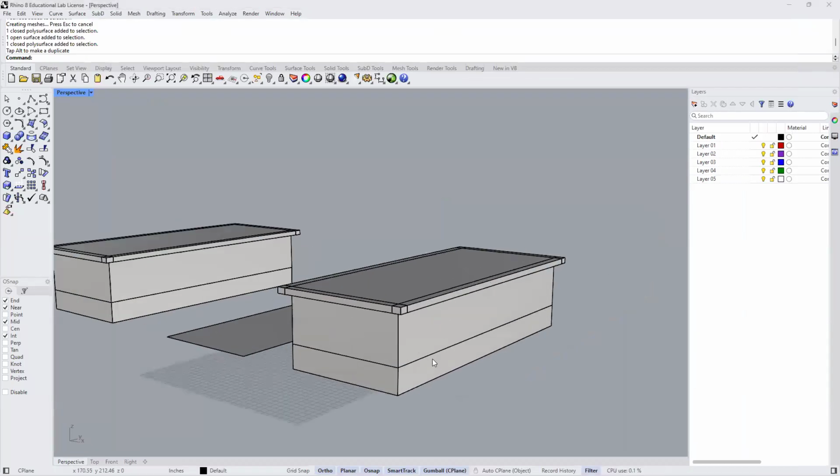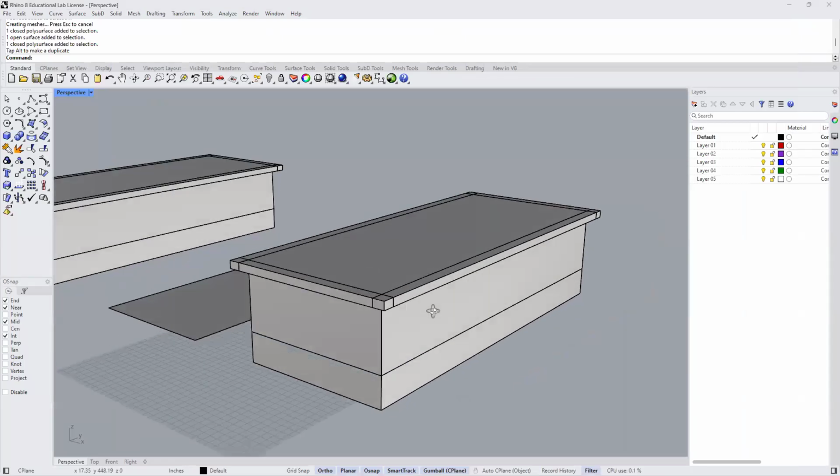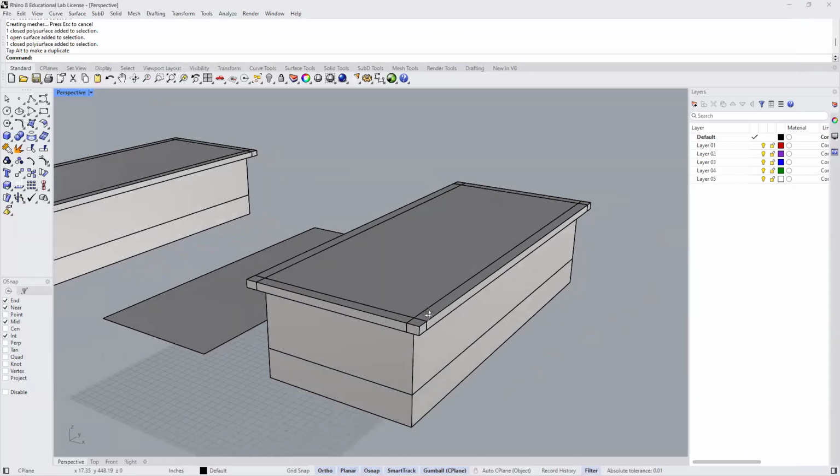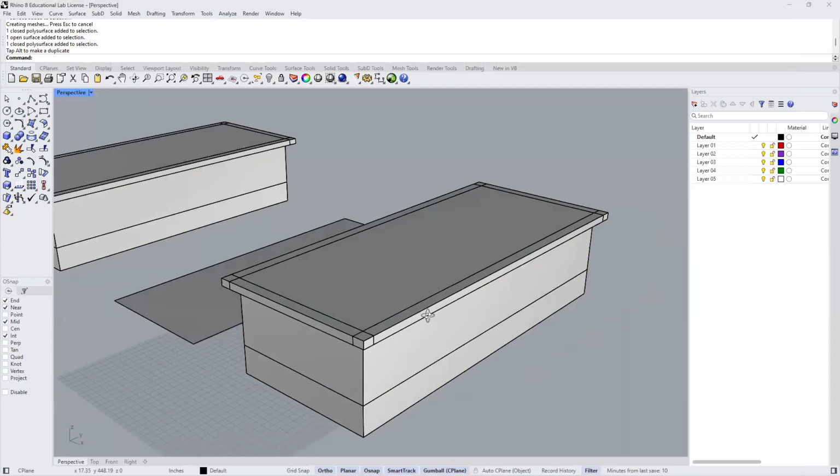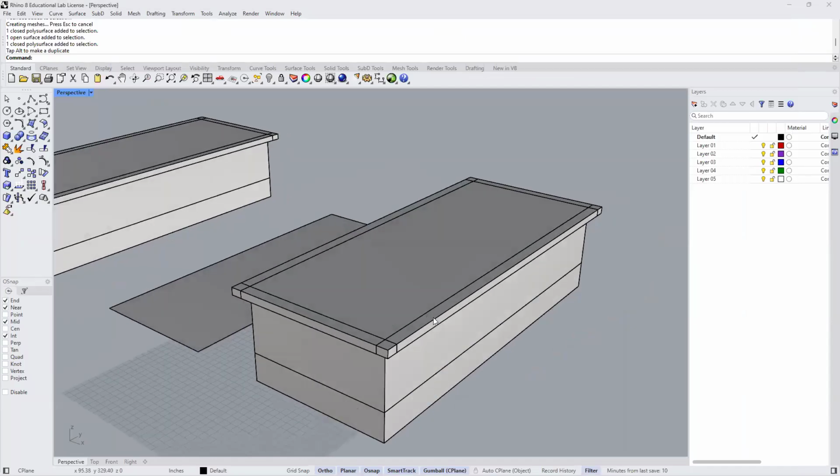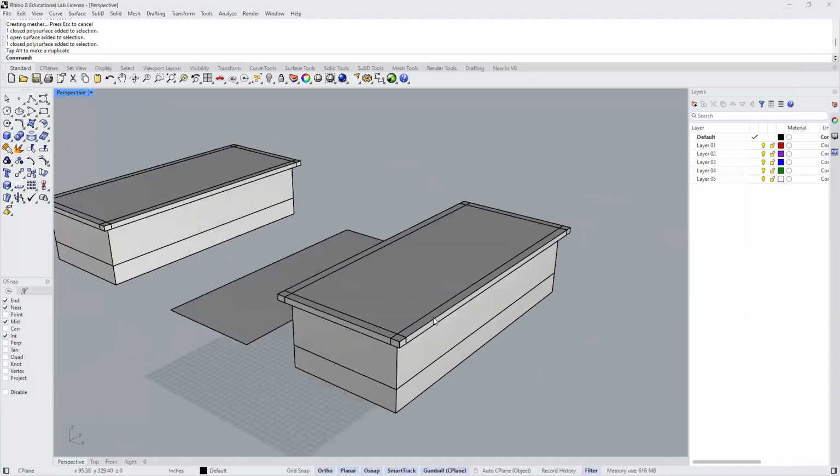And before I do that, I have many lines here. And one of your classmates asked me this question last week, and I said, I'll give you the answer now, but I will share it out on a tutorial. So here we go. What I need to do here is really just remove all of the extra line work that's not needed. So there's a command, and it is merge all coplanar faces, and it's one single word, coplanar faces. You can see it appearing there at the top, so I'm just going to finish typing this out.